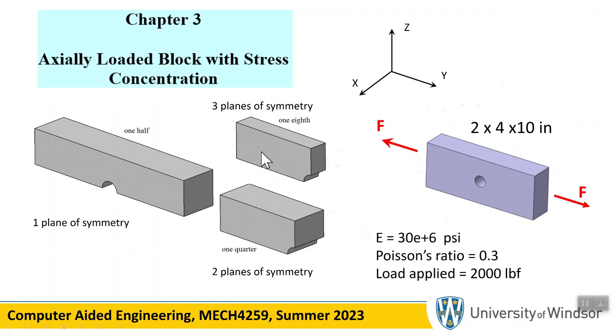The other thing is that just cutting it is not good enough. You can't just take 1/8 of the model and then say, okay, let's apply load. These artificial surfaces that are created, the ones that you cut by the XY plane or the YZ plane or the XZ plane, must be restrained somehow, and those are roller supports or symmetry constraints. CATIA does not have something called a roller, it's called a surface slider. So don't just take a portion of that geometry and pretend that you're all good. When you introduce an artificial face into that geometry because of symmetry, you have to apply the proper restraint on it.